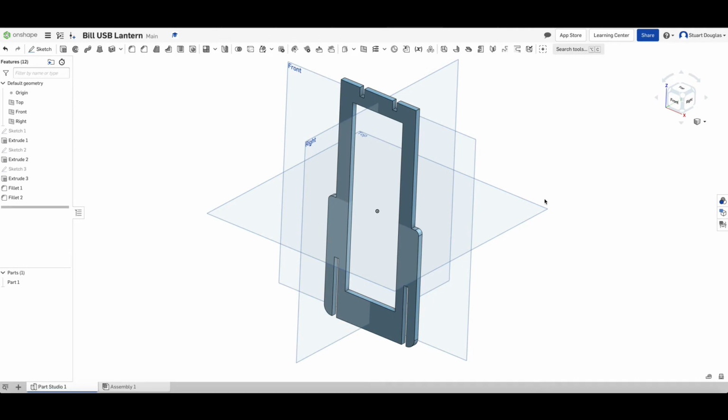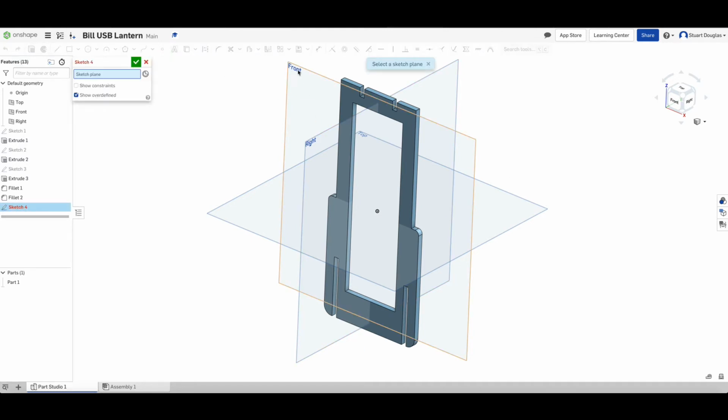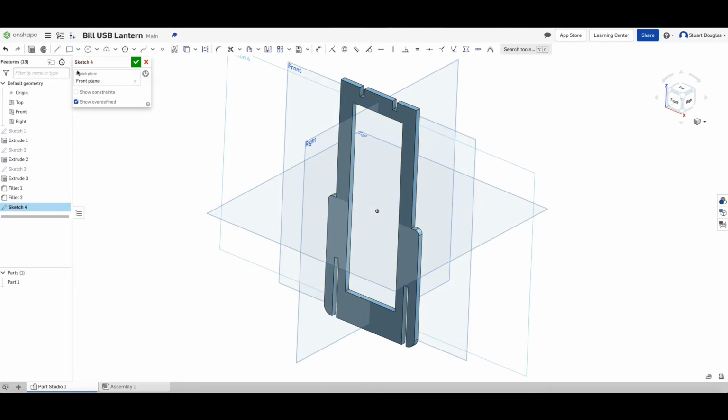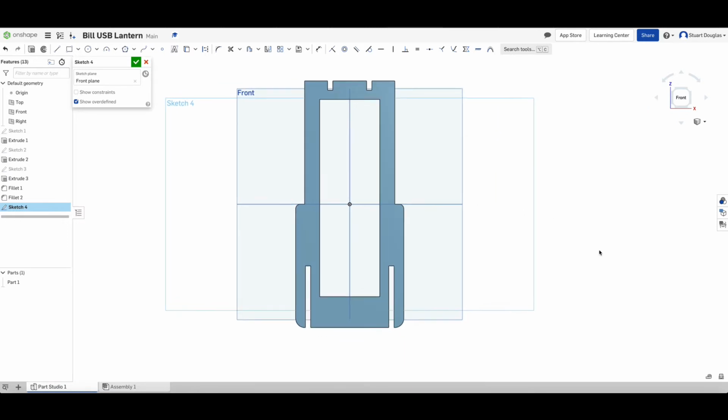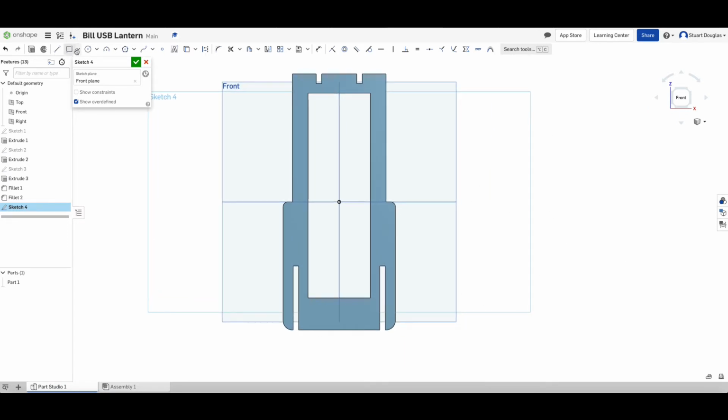Add the matching corresponding second panel B design. To do this, click on the sketch tool, click on the front datum. Front plane is selected. Let's click on the front of the cube. This time we're going to draw our panel just at the side of our work over here. To do that, draw a rectangle again, and we can make the rectangle quite near our first one. Just going to click once and click a second time.